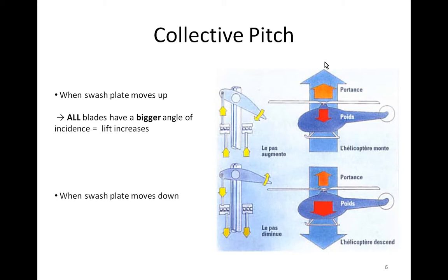When the swash plate moves down, all the blades have a lower angle and the pitch decreases. Then the lift decreases too. If the lift is less than the weight of the helicopter, then the helicopter moves down.